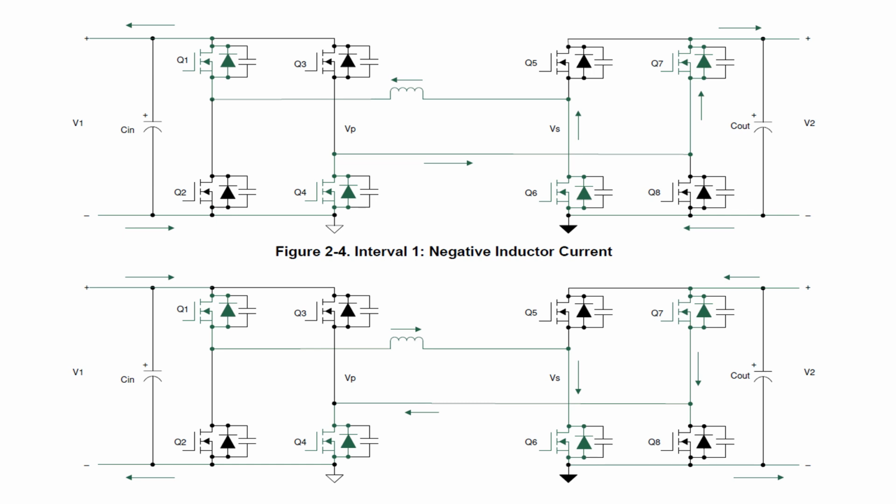In this video we're basically going to look at the dual active bridge and the sequences involved in the switching operation of a DAB, or dual active bridge, converter. The converter shown in the diagram figure here is a bidirectional dual active bridge converter, simply meaning that power can flow